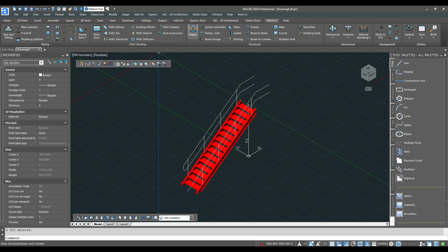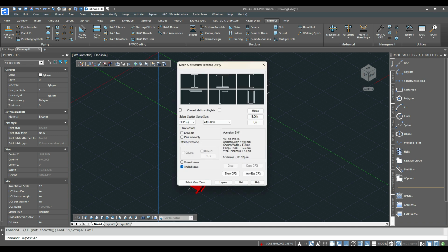There are steel shapes. Now, South Africans, you would love this. RSA steel sections. Guess what? I've got an equal angle, under about 10. These are the standard sections: 40 by 6. Unequal angle, you've got 90, you've got your sections there, 60 by 50 by 8, etc. Beams, once again, IPEs, the whole range, IPE 200, etc. Use that, and once again, you can draw in 3D.